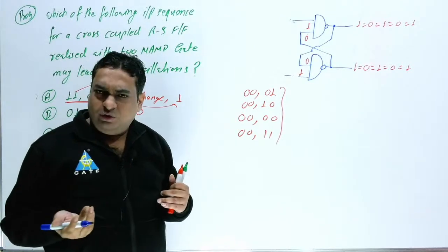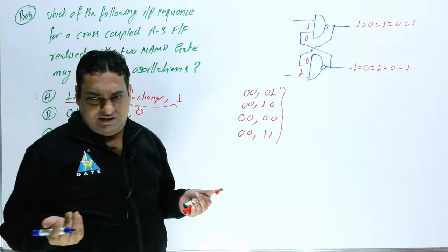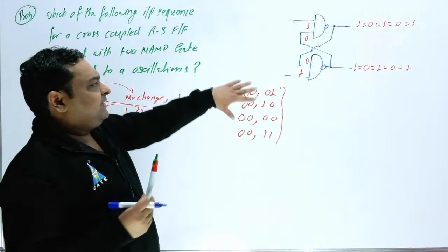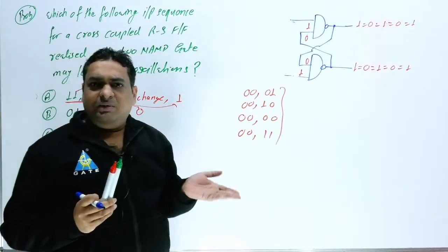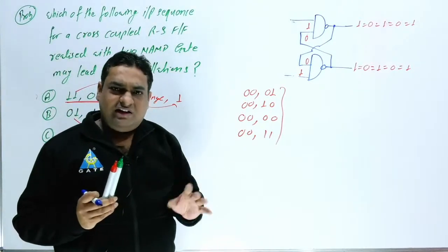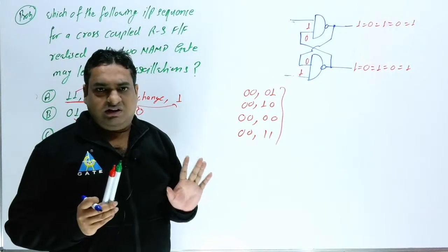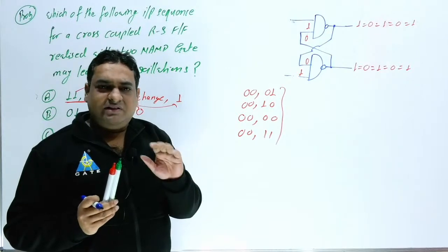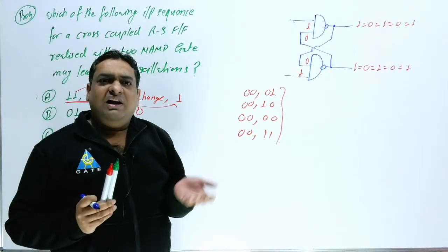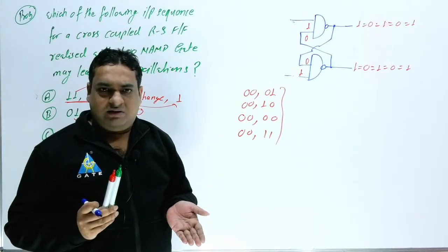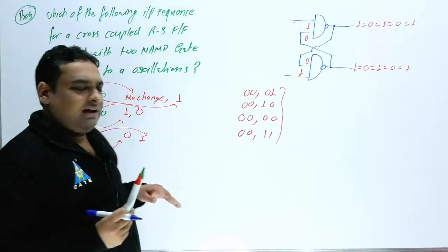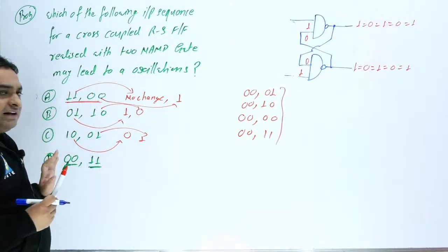It can be an active low category or an active high category, it can be anything. Here we have assumed the active low category, because the examiner clearly mentioned the cross coupled NAND gate. If the examiner provides only an RS flip flop, we can assume active high. So if the question was active high, the answer can be 1 1 and 0 0.